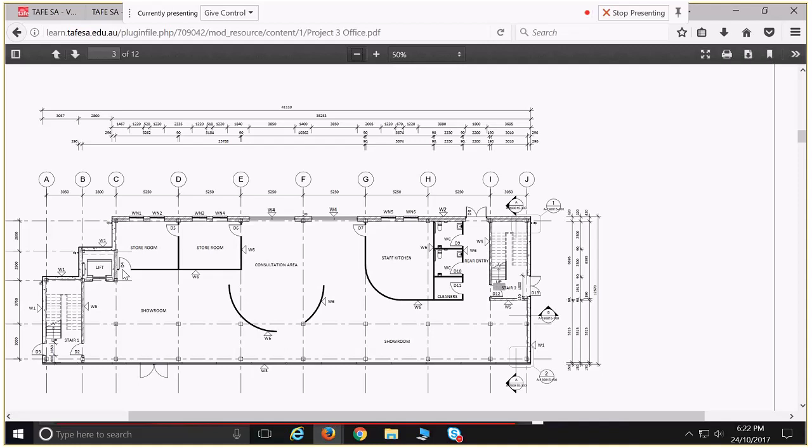So you're going to have to calculate floor areas. In the example given in the assignment, it says 250 square meters of floor area. Now that's not significantly different from the answer you should come up with here, but it is slightly different. So I can see who's calculated the floor area and who hasn't. That can be done by just simple maths, by multiplying this dimension by that dimension and minusing this area, or however you wish to approach that.